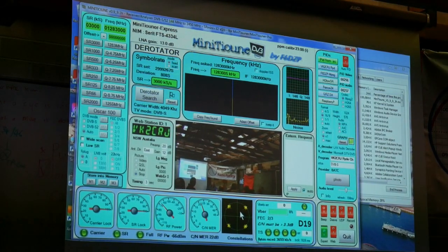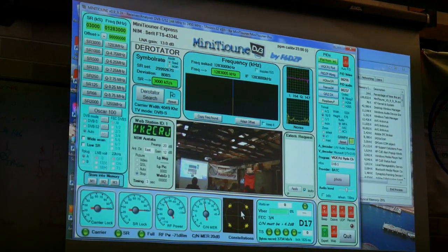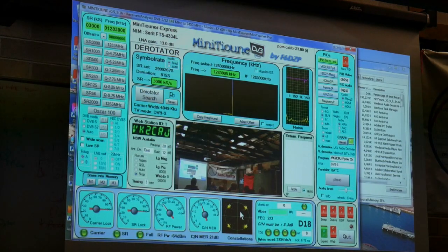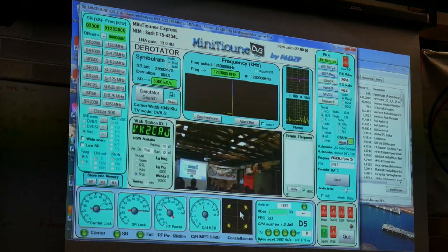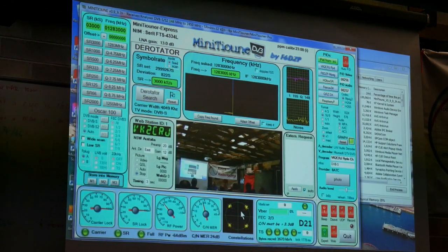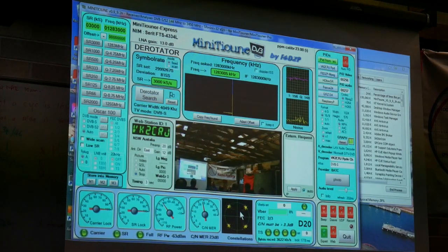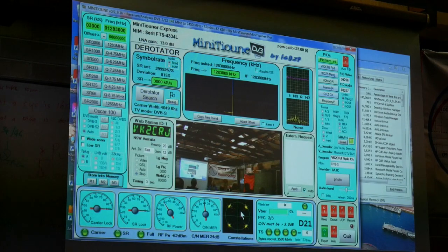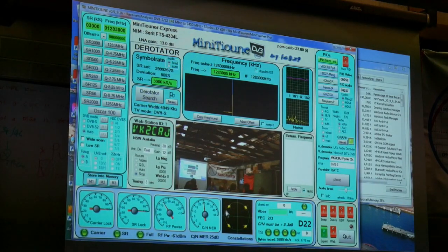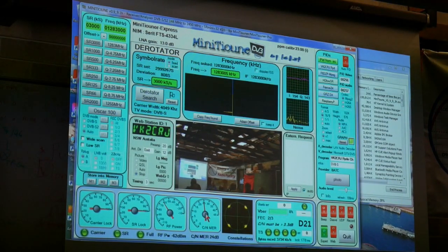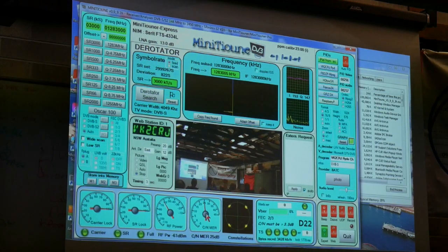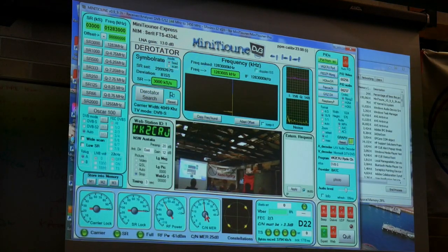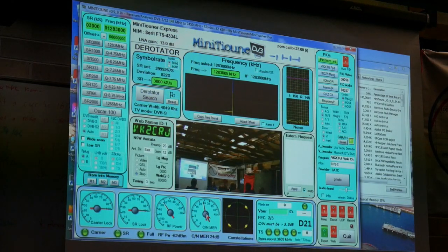But I'm just receiving it on that bit of wire, which isn't even a quarter wave. These tuners are pretty deaf though, but you get the idea. So you can see it's QPSK, carrier to noise MER 25 dB. That's a very respectable signal. The constellation was quite noisy. Oh yeah, well it's live. This is a live shot of what it's receiving, right?